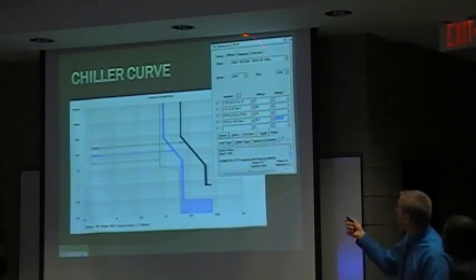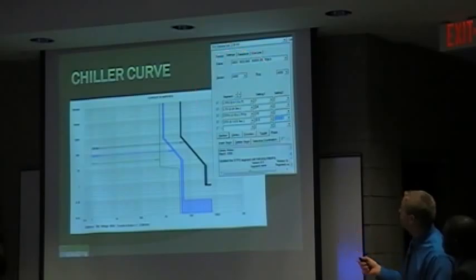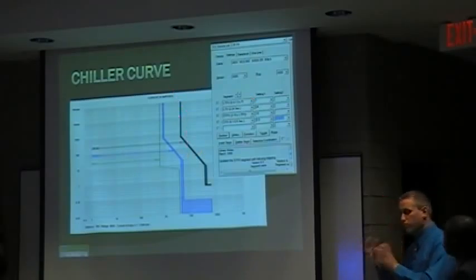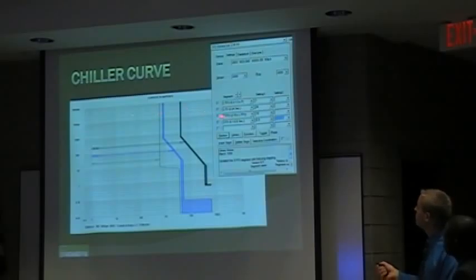Then the input data that you can put in here is long time pickup. We set that at 1, which is the 4,000 amp setting. The long time delay, we have it set for 24 seconds, so if there were an overcurrent, it would trip within 24 seconds. The short time pickup, we set that at 10.